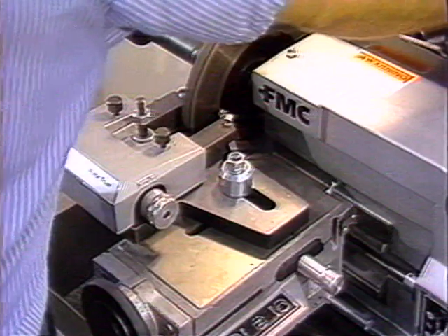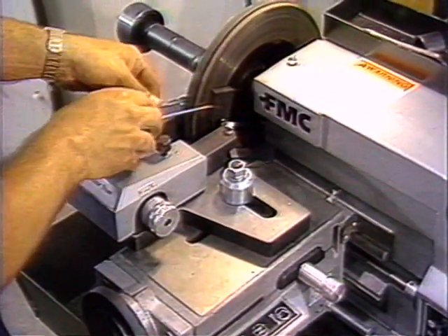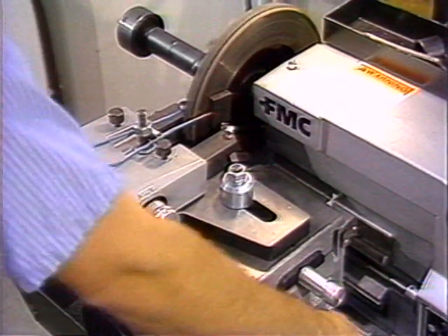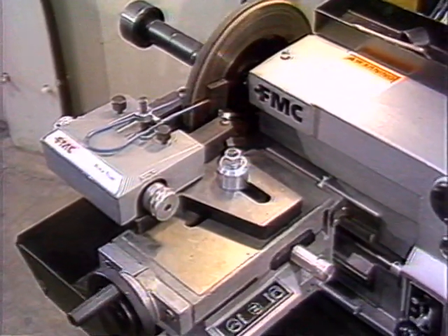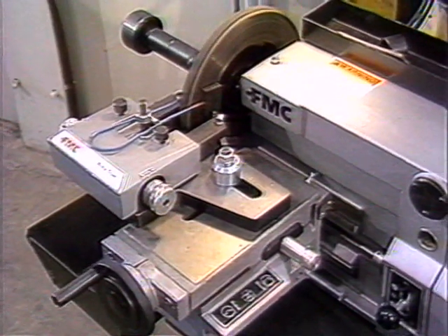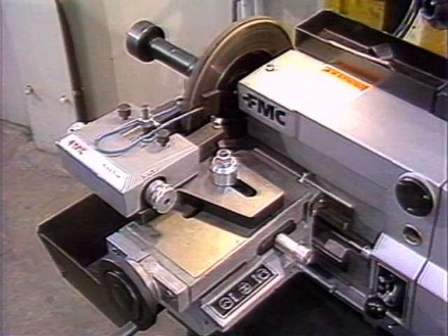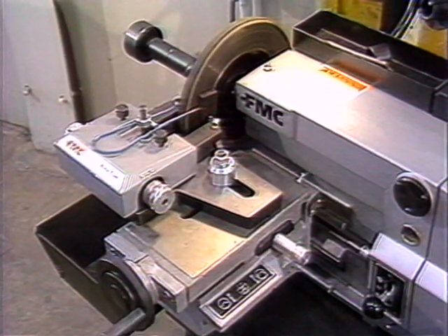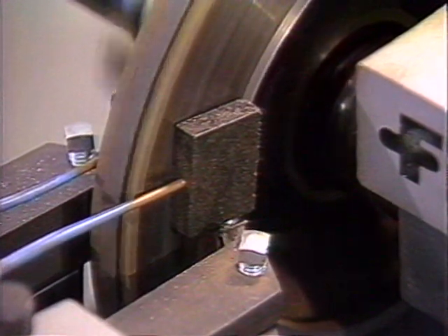Make sure, however, that you are not removing too much material at one time. Refer to the lathe instructions for details. Generally, most lathes will cut about 40 thousandths of an inch during each cut. If you must remove more material, make 2 cuts. Rotor and lathe damage can result if you try to machine off too much metal at once.